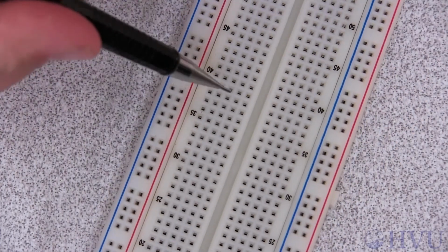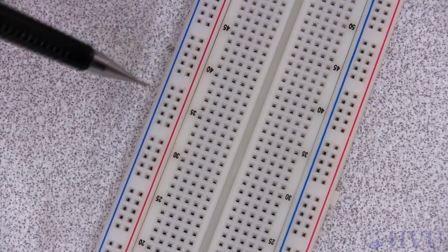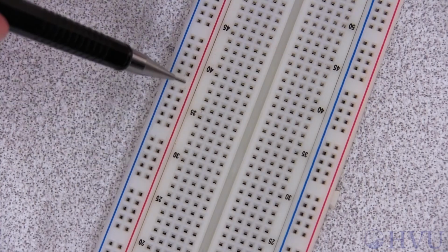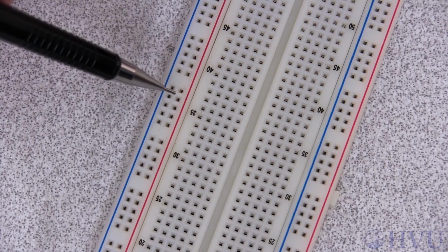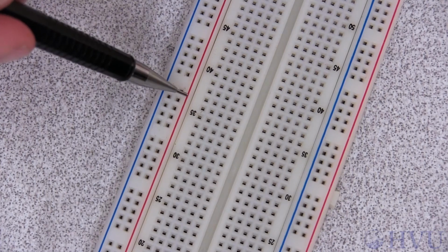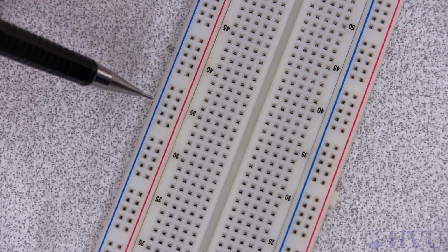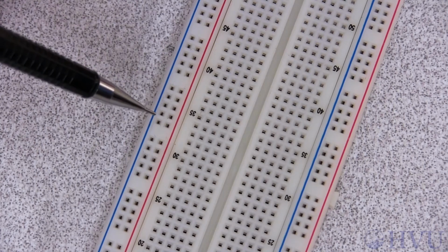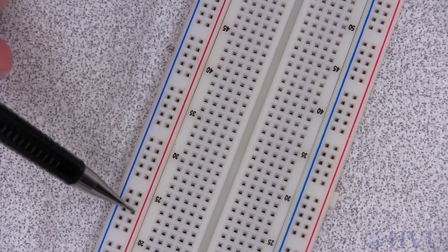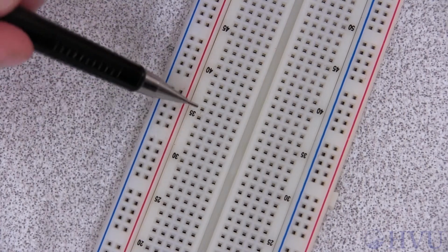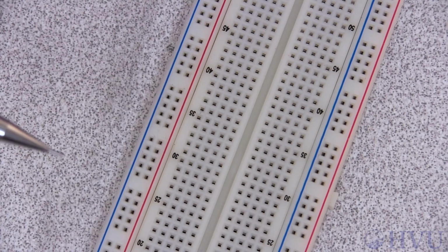Many breadboards will have what are called bus strips running along the entire length of the breadboard. Each bus strip will generally have either a blue or a red line next to it. All of the holes in each bus strip are electrically connected. These strips can make it easy to connect the same voltage to multiple nodes. This is used mostly in larger circuits.